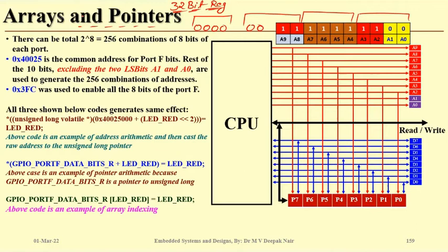in that case, if you read now, this combination 0011 is 3, 1111 is F, and then 1100 is C. So what does that mean? It means all the combinations can be generated by using 3FC in the port F. Okay, I will make it more clear.